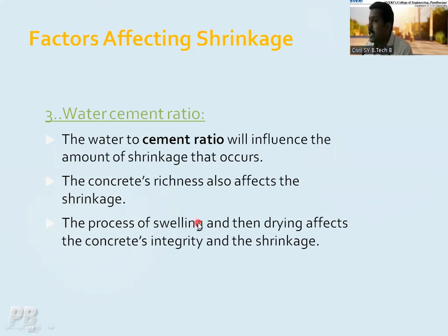That is, there will be swelling. But after that, maybe after the rainfall, the temperature goes up to more than 40 degrees centigrade. In the summer season the temperature goes on increasing. So what happened? Due to the rise in temperature, the water gets evaporated from the concrete body.